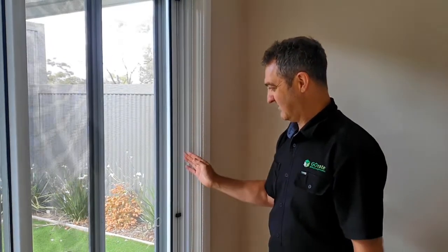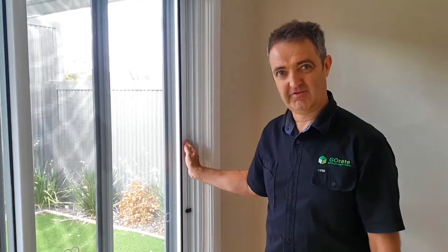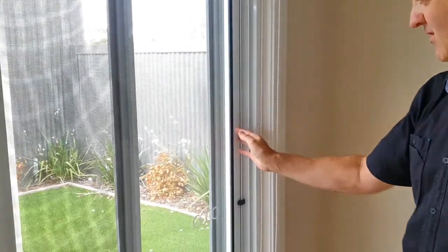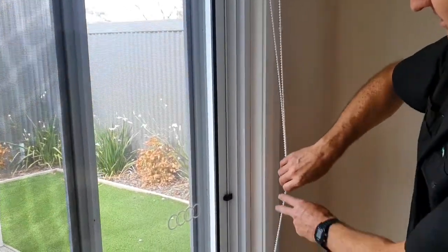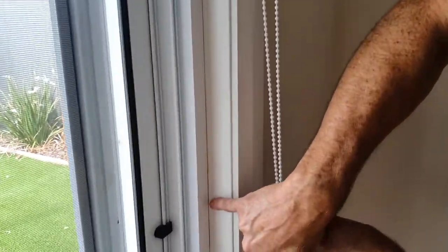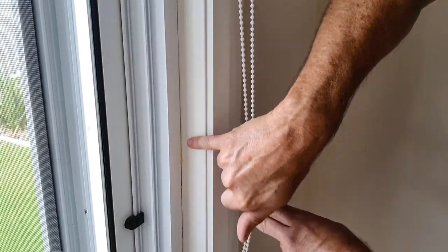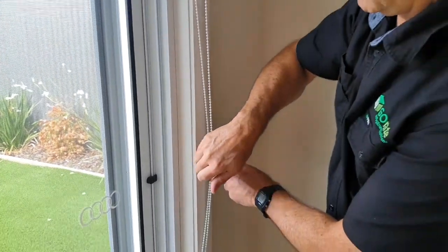But the other thing is, between the actual aluminium frame and the window reveal, there can be a gap as well. So if you're going for a really high performance type of house, you can end up with leakage in this little point here. So if you gasket the fin of the glazing to the reveal, you can eliminate that leakage point as well.